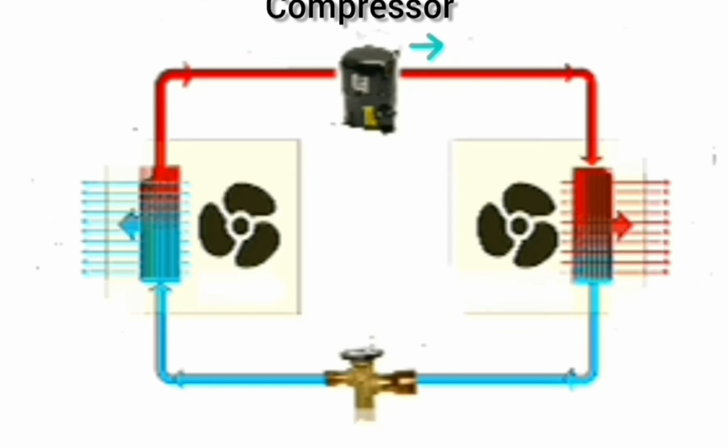The process of compressing gas refrigerant will cause the refrigerant to gain heat, because when you increase the refrigerant pressure in a fixed volume, it will cause the temperature of refrigerant to increase, and vice versa. So, at the outlet of compressor, we'll have high pressure, high temperature gas refrigerant, which goes to the condenser,